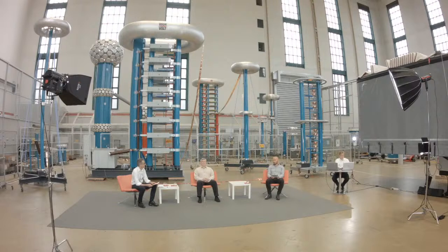We need them almost all, but I have to say that, in contrast to the others here, I'm not so much a friend of interpreting the pattern and saying, okay, this picture belongs to this failure or error, because at the end, if you have a 25-ton high voltage component, you don't want to know if it's a void or not. You want to know where it is, if it's a problem. So what I do is an electrical measurement. I have a value which is in the contract, and if I'm above, I have a problem and I have to solve it. So in the next step, what I want to know is: is it inside the component or outside?